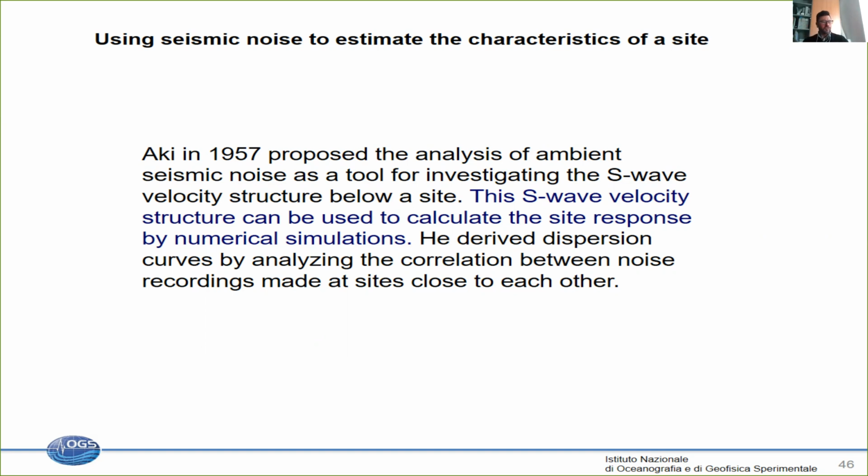So if you read the Aki paper from 1957, which is in my opinion a very nice paper to read, he was introducing the analysis of seismic noise as a tool for investigating the shear wave velocity structure below a site. And of course, if you know the shear wave velocity structure, you can then calculate the response using numerical simulation.